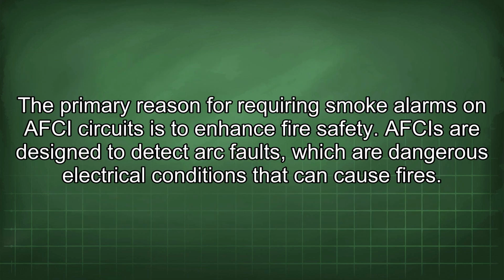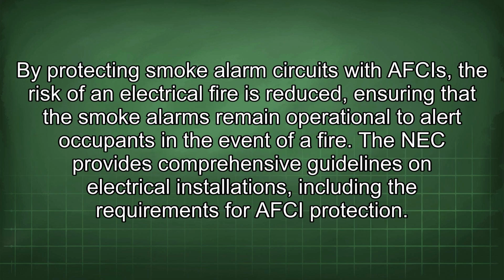The primary reason for requiring smoke alarms on AFCI circuits is to enhance fire safety. AFCIs are designed to detect arc faults, which are dangerous electrical conditions that can cause fires. By protecting smoke alarm circuits with AFCIs, the risk of an electrical fire is reduced, ensuring that the smoke alarms remain operational to alert occupants in the event of a fire.